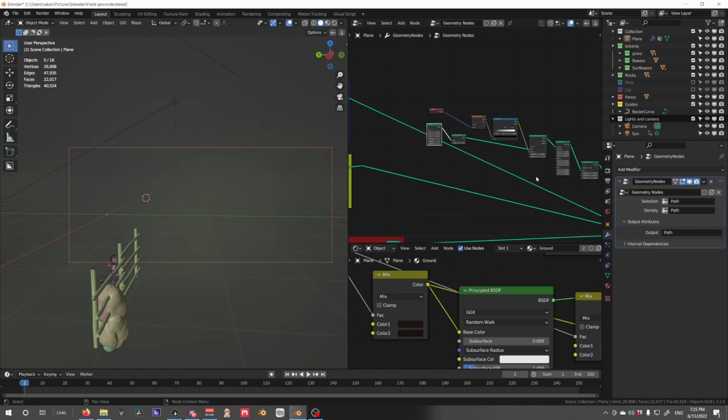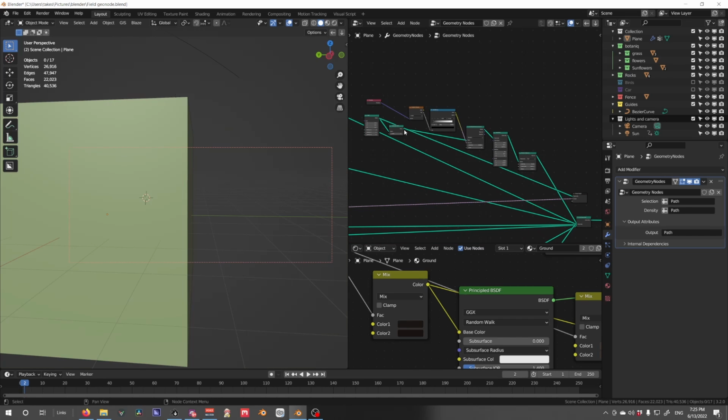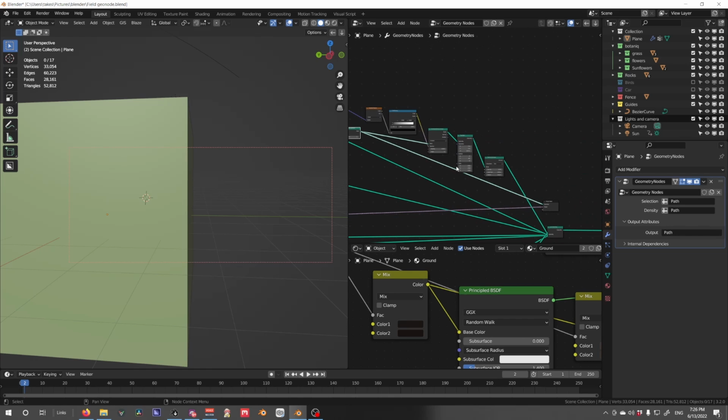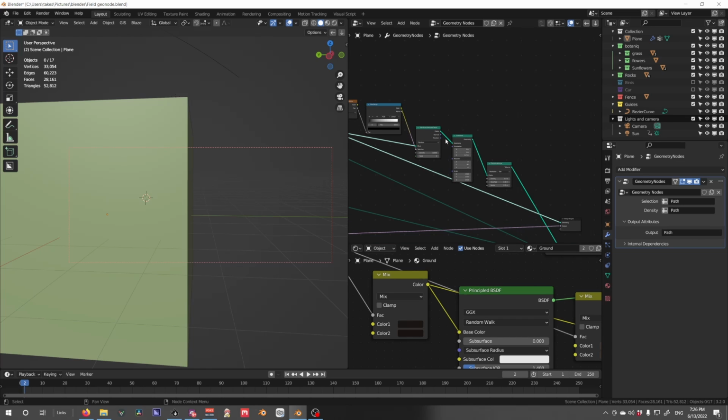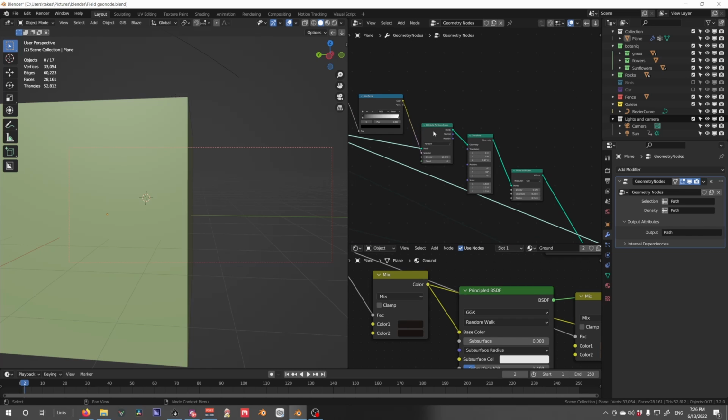So let's break down what this mist is. First I brought in a cube. I subdivided that cube using subdivide mesh to a level 5. This just subdivided the mesh as if you just pressed tab, right click, subdivide. It's not subdivision surface. It doesn't create a rounder edge.